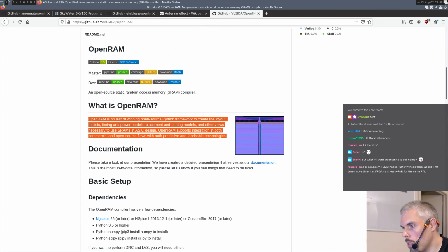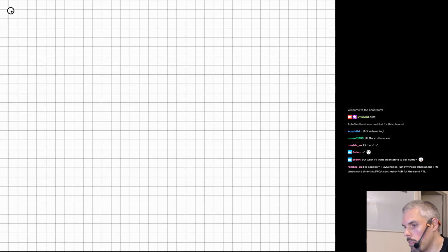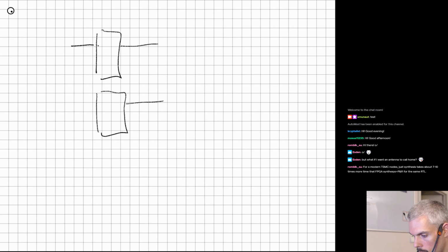So what you end up implementing is basically you have your write port, and then you have your read port 0 and your read port 1, and you write the same data to two RAMs at the same time. You could do the same thing on an ASIC, right? But of course, that would take twice as much area. That's the first option.